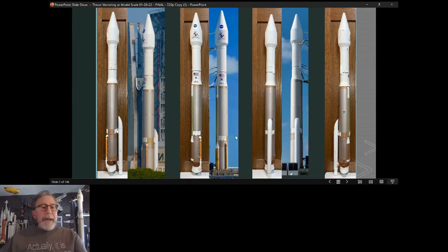So this is the rocket we're going to be talking about today. This is the model on the left, and then an actual photo of the rocket prototype on the right. It's 1:48 scale, single SRB, and the model is thrust vector controlled. It's United Launch Alliance's Atlas 5 booster. 411 is the designation, meaning a 4-meter payload fairing, 1 SRB, and 1 Centaur motor.